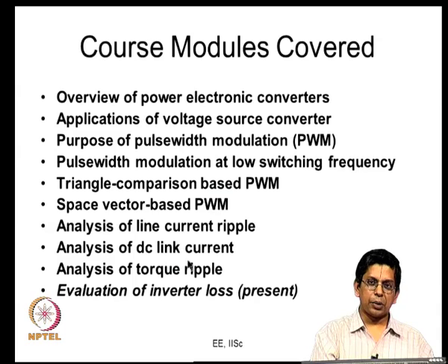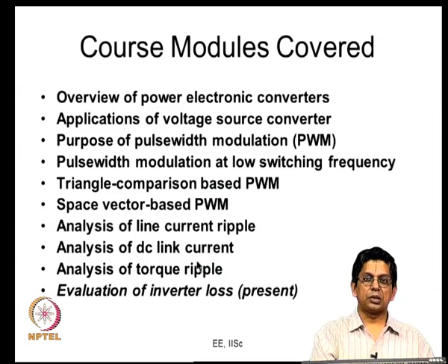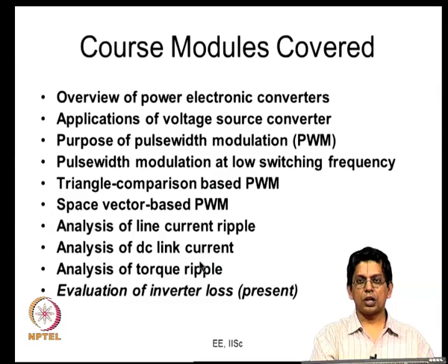So, in the electrolytic capacitors you have some amount of loss happening, which is represented by what is known as the equivalent series resistance, ESR. So, once you know the RMS current, you can square the RMS current and multiply by ESR to get some measure of how much loss could be expected inside the electrolytic capacitor.